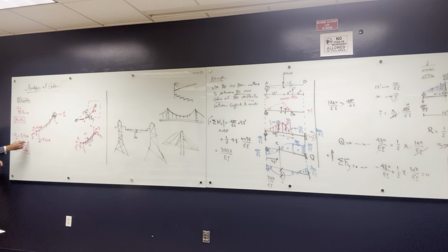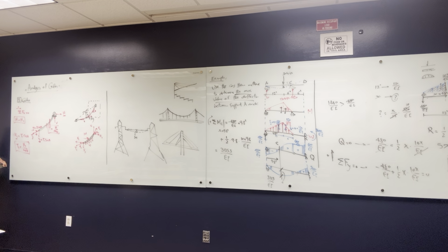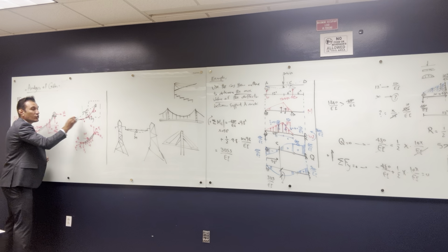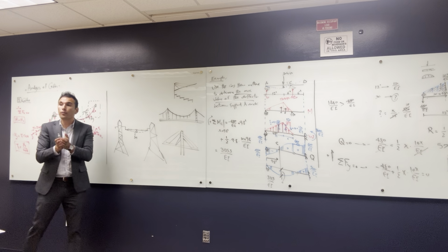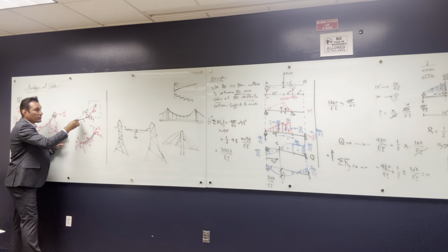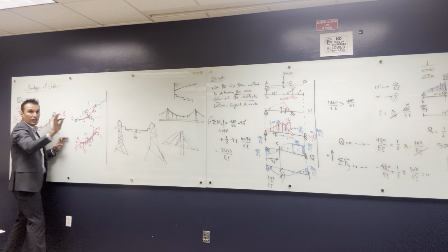And actually that is the general rule if you want to know the tension at any cross section in the cable. The tension here is going to be equal to the horizontal component here over cosine theta at any cross section. So if you want to find what is the tension, and that's actually the important component that we are looking for, first you have to know what is the horizontal reaction here and what is the horizontal reaction here. Okay, that's the very thing I know.